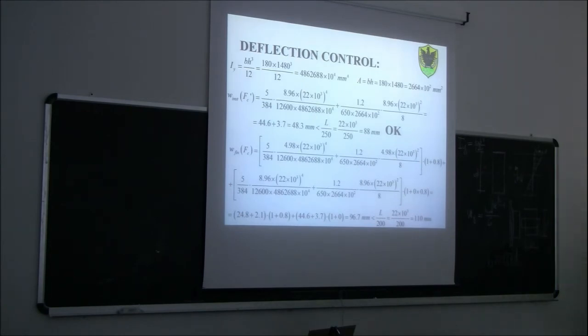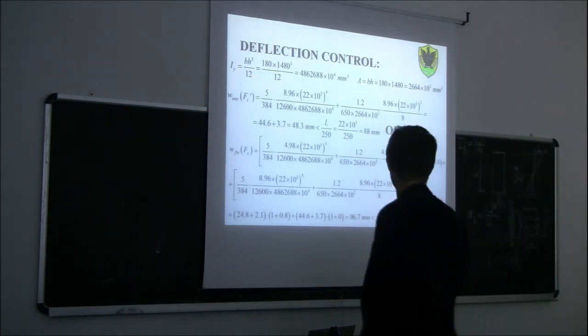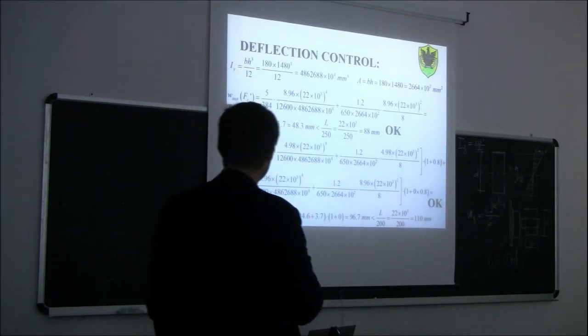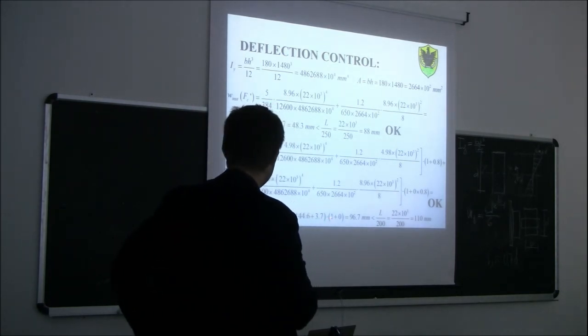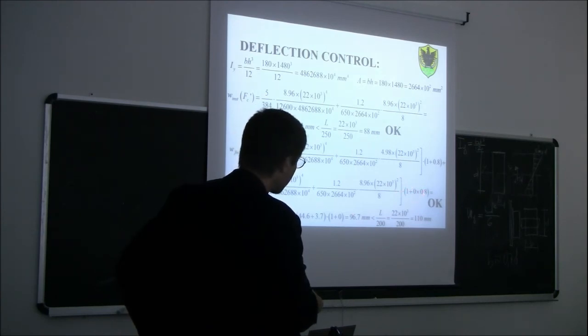Okay, now we want to calculate the long-term deflection, so the final deflection, but again we put all the numbers inside. And in the end, you see, we find out that, as we already observed before, the snow load doesn't have any creep contribution, because here you find this creep contribution is 0, not because the creep coefficient is 0, but because the psi 2 coefficient is 0.